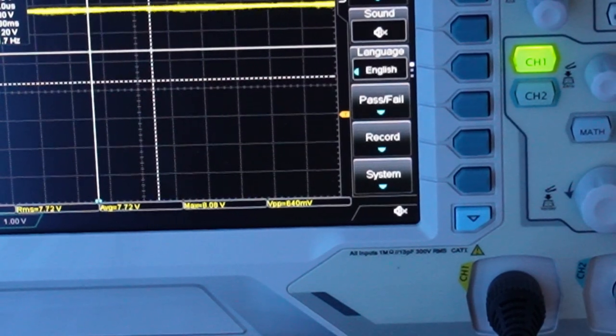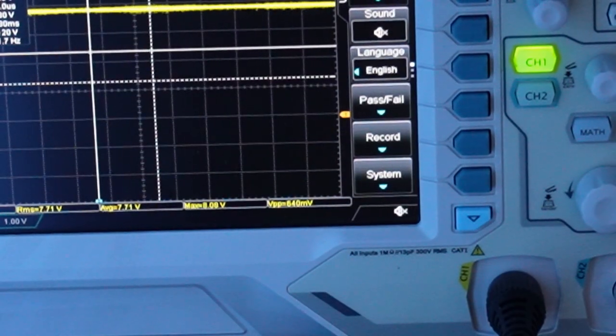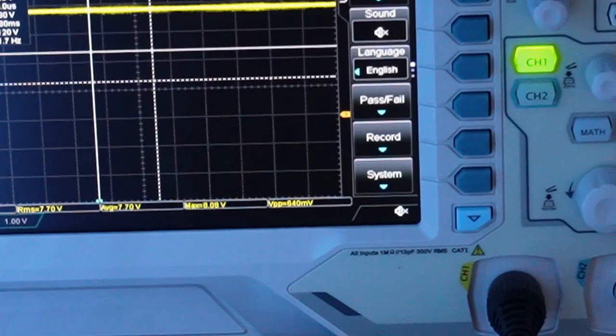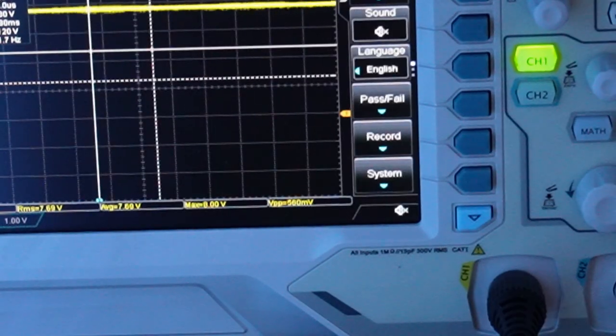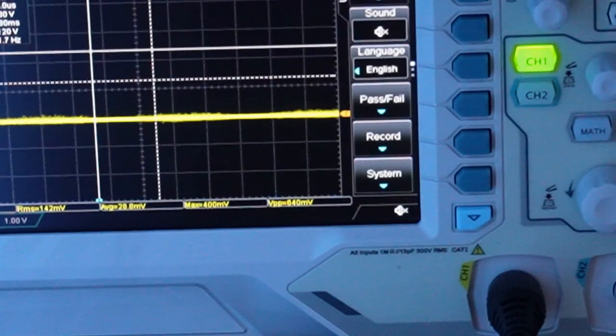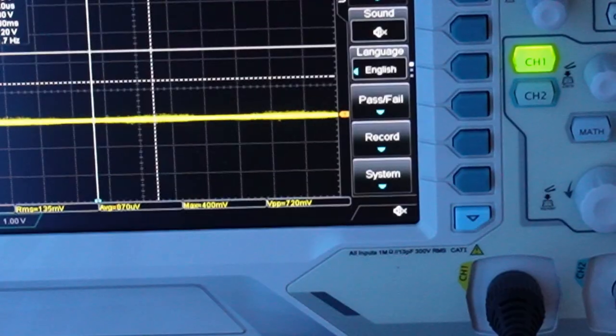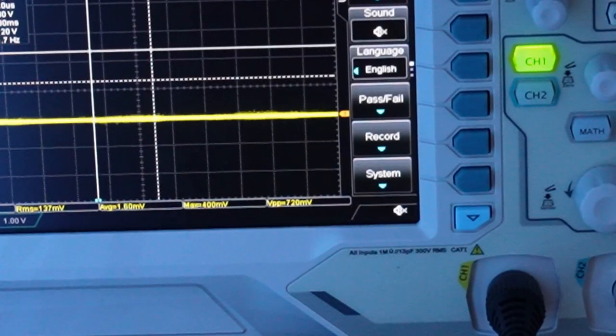But we do see that it's around 53 milliamps, so it is pretty close to the actual collector current we wanted. Besides that, I'm going to turn this off because it will get pretty hot. Those resistor values are not built for it. But as you can see, we selected some values here and it worked out.